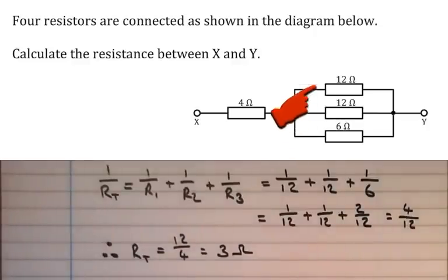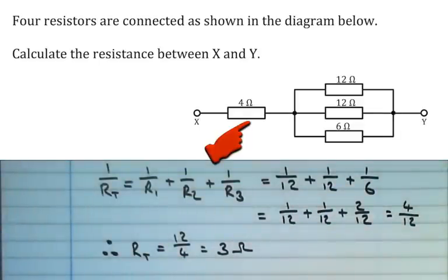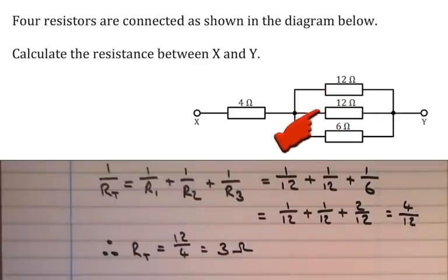This one obviously just goes over the order, if you do have a circuit like this which has a parallel component and a series component. We've just worked out the effective resistance of these 3 resistors. So if you're given a circuit like this, then you would always work out the effective resistance of these resistors on the right hand side. Then you would add the resistor on the left. Sorry, we worked out that this was 3 ohms, didn't we? Yes, we did. So this would be the 3 ohms plus the 4 ohms, would be 7 ohms. So in total this would be 7 ohms.